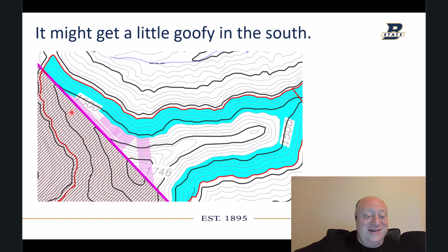And so what I tried to do was, once you get started, I was trying to get as many holes as I could in that are really long, so that you can get some highwall opened up, so that you can keep mining, right? So I showed coming right here to this corner, and what you would do is kind of just blast a face here and then I'm putting the holes in 1,000 feet long right along the property line and put in maybe 3 or 4 there to get you a couple days to get out ahead, and then start out with some short holes this way.